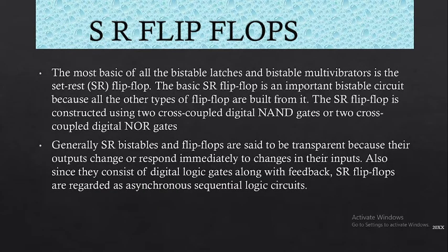SR flip-flops. The most basic of all the bistable latches and bistable multivibrators is the set reset flip-flop or the SR flip-flop. The basic SR flip-flop is an important bistable circuit because all the other types of flip-flops are built from it. It means that SR flip-flop is the most basic type of flip-flop and it is a building block for all the other types of latches and flip-flops. That means we can use SR flip-flop to make more advanced latches and flip-flops. So we need to know about it in detail.